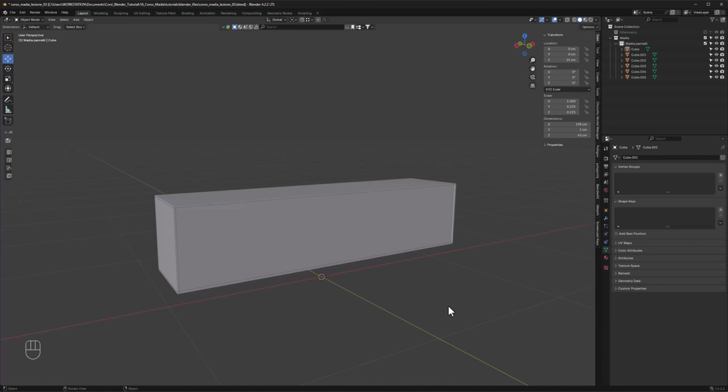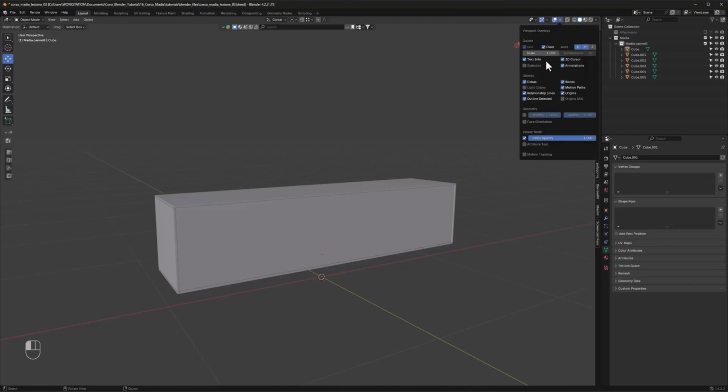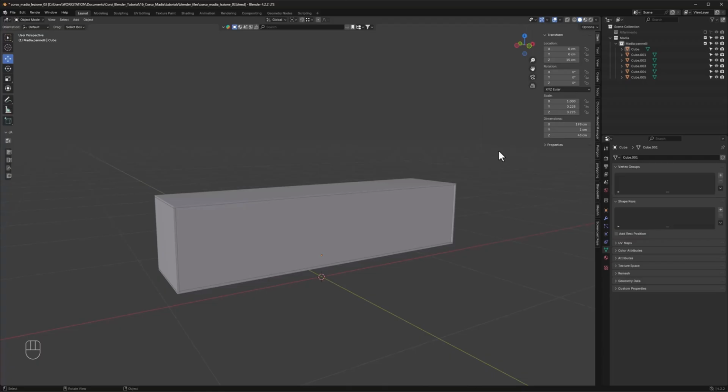Given the importance of normals, it might be useful for us to create a shortcut to quickly access the face orientation command. Reopen the Overlays menu and place the mouse cursor over the face orientation option. Right-click and then select Add to Quick Favorites. From this moment on, whenever we need to access the face orientation command, simply pressing the Q key will immediately activate the normals check. In the same way, by pressing the Q key, we can quickly deactivate the command.